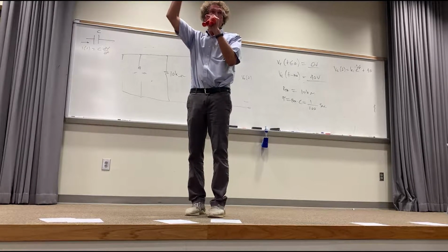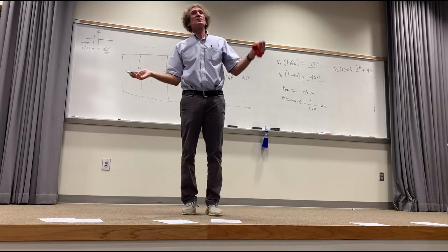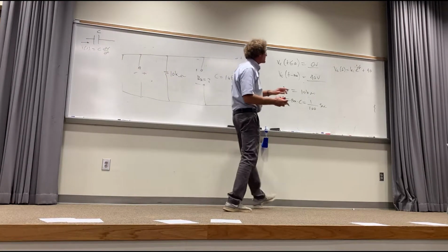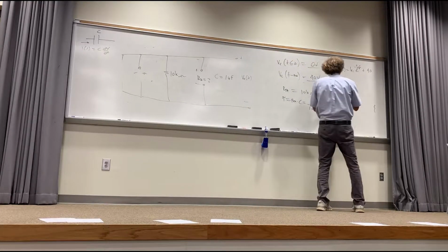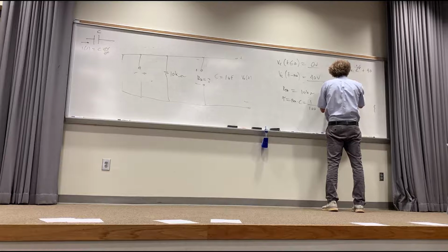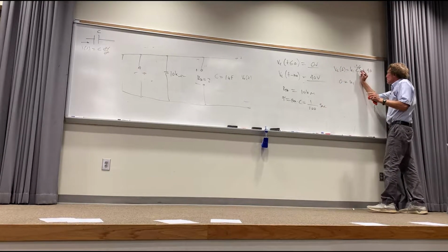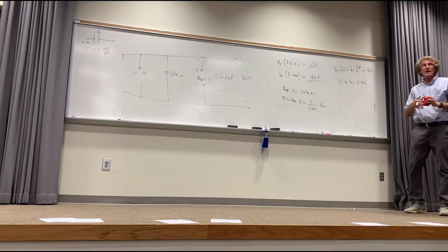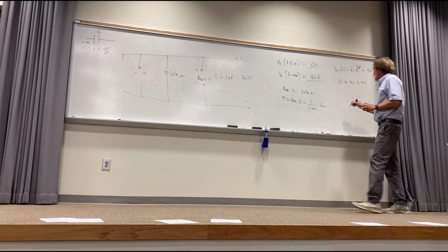You follow me? What it amounts to is the voltage at t less than 0 has to be the voltage at t greater than 0. We know the voltage at t less than or equal to 0 is 0 volts, right? Now when I put down here 0 is equal to K1 e to the 0, so t equals 0, that's just 1 plus 40. How many see that K1 is minus 40? Everybody on me with this?